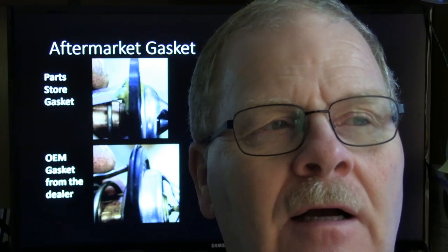On that particular one, we heated that thing up, and the thermostat opened at about 210. And I said, well, I don't know exactly what that means, but I know that the engine was running too cold. So I went ahead and just got another thermostat, because they don't cost much, and I put that in there, and it warmed right up.